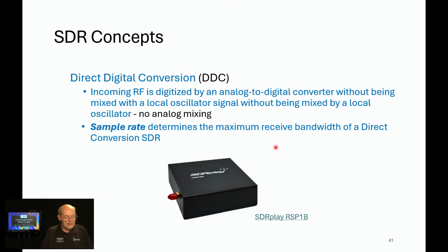Now sample rate, I think we touched on this, determines the maximum received bandwidth. No, actually we didn't. It determines the maximum received bandwidth of a direct conversion SDR, software-defined radio. In your world, Gary, those are called slices, I think, aren't they? In the Flex radio. Yep. Determines how much bandwidth you can see.